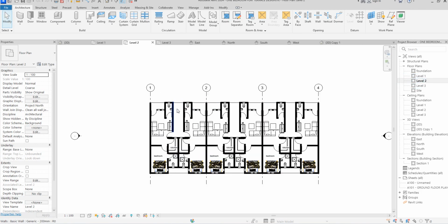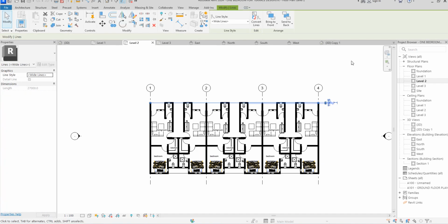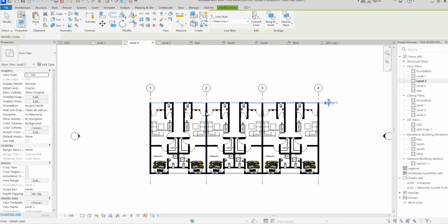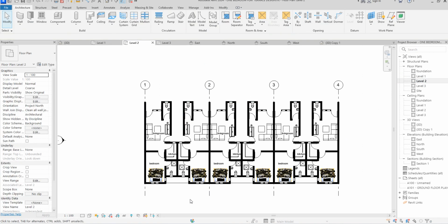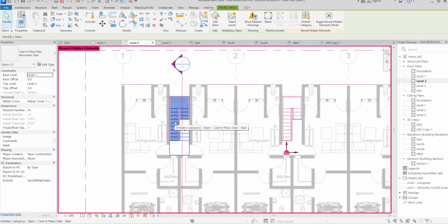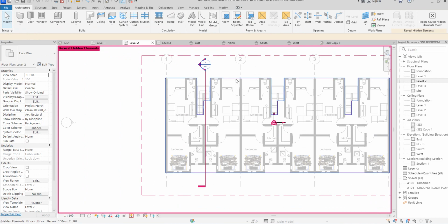So now what we do here is that we have created the staircase, but it's not reflecting here. So what is the issue? What we need to do first, delete the line. So what is the major issue here is that we are going to check our hidden. So in the hidden position we have this. So we are going to say unhide everything so that everything will be visible on unhide up. So now the next thing is the floor.